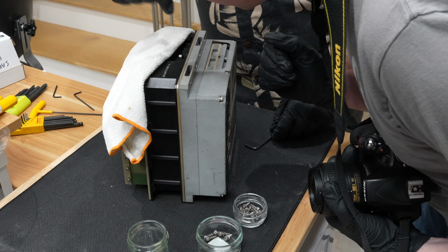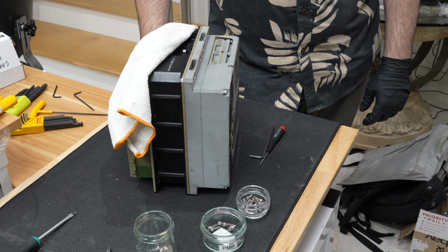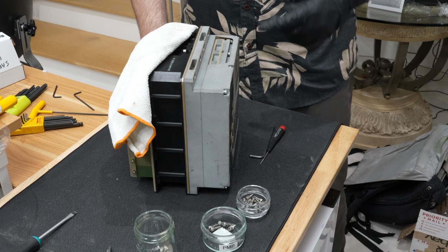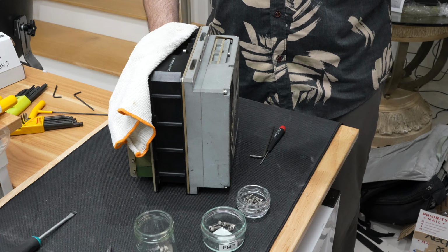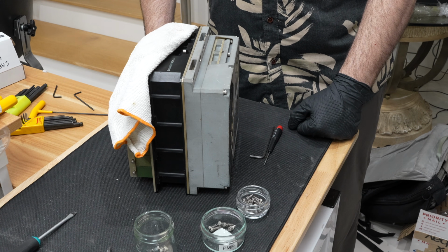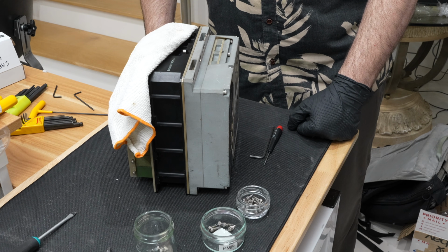We need to be able to push it back down, I think. Yeah. So there's just too much force on it and it's pushing the E-clip out of the groove. It was already bent from whenever it was last disassembled, I assume. Yeah. Someone probably ripped it out or something. If you don't know that that's there, you might just say, I'll take out the screw. Oh, they pulled the E-clip out too far. Yeah, that would definitely do it.